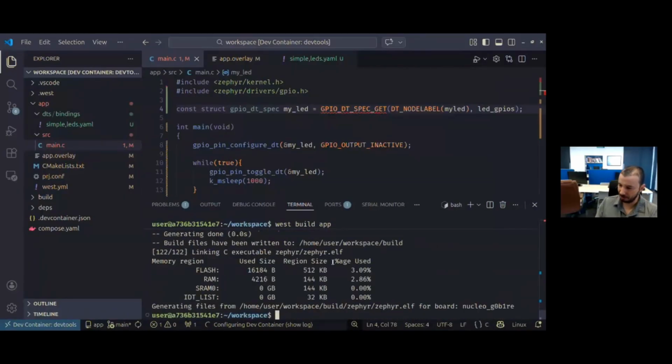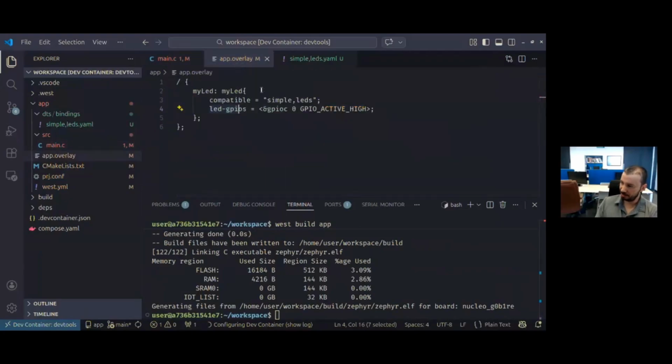And voila, there's no error. All right. So the name is going to be accepted by the build system only if it ends with GPIOs. You can use as many letters as you want, or any other names that you like, but it is mandatory to end the name of the property with the word GPIOs, right?